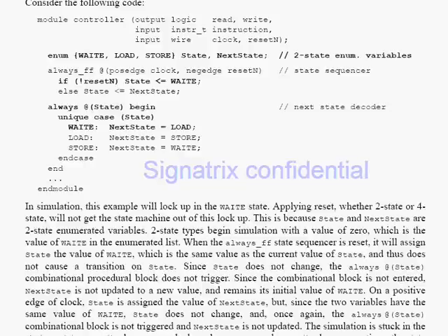When you apply reset, it is again the same value, so there is no transition between these two. So this block will not execute. But in Verilog, the initial value of state is 2'bxx. After that, if you come to 2'b00, there is a transition, and that's why this block will execute. So this is the deadlock condition.